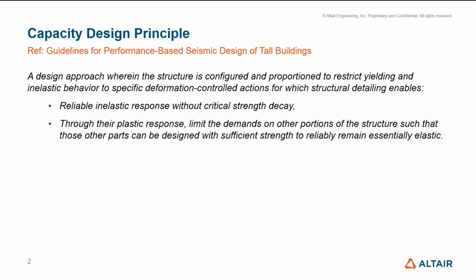So it is the design approach wherein the structure is configured and proportioned to restrict yielding and inelastic behavior to specific deformation control actions, for which structural detailing enables first, reliable inelastic response without critical strength decay, and through their plastic response, limit the demands on other portions of the structure such that those other parts can be designed with sufficient strength to reliably remain essentially elastic.